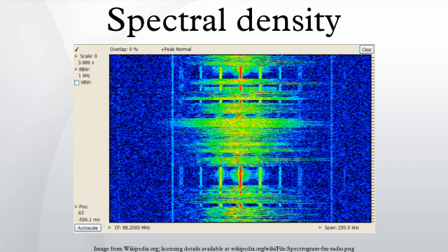Explanation: in physics, the signal is usually a wave, such as an electromagnetic wave, random vibration, or an acoustic wave. The power spectral density of the signal, when multiplied by the appropriate factor, describes the power contributed to the wave by a frequency, per unit frequency. Power spectral density is commonly expressed in watts per hertz. For voltage signals, it is customary to use units of V²Hz⁻¹ for the PSD and V²sHz⁻¹ for the ESD.